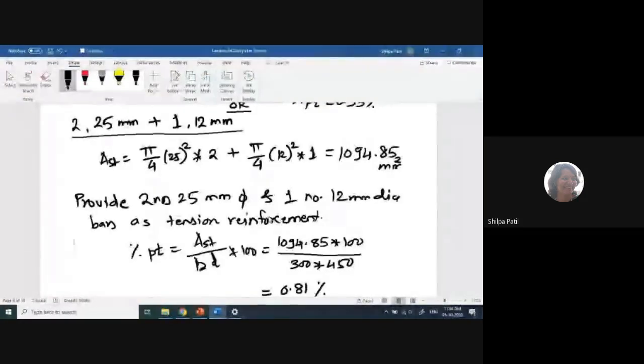There are four different criteria now, and for that we need to calculate the width of the beam. Anyways, you can have that check also here, and based on that we can find out what will be the spacing between the bars of the steel, but you can skip that step here.